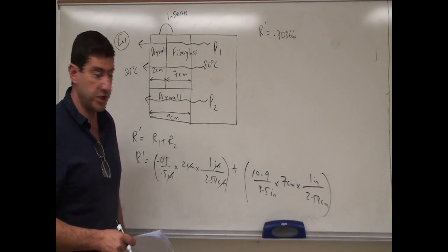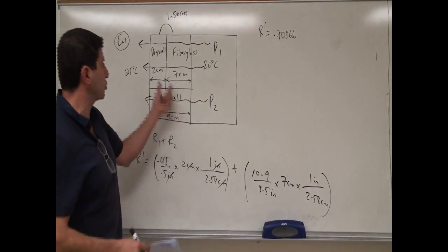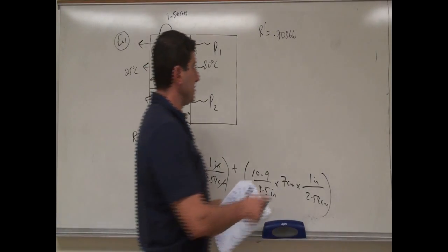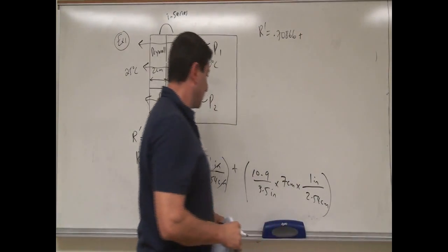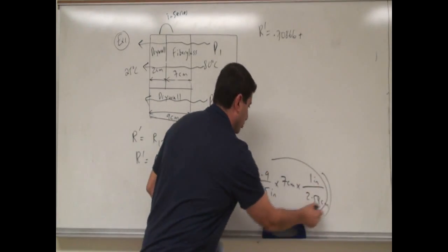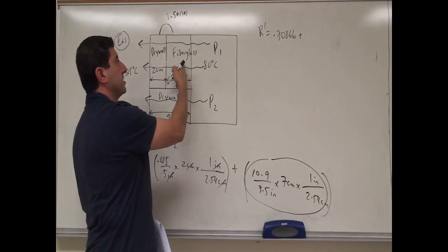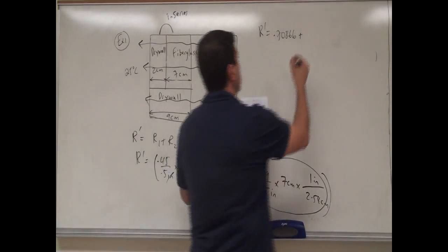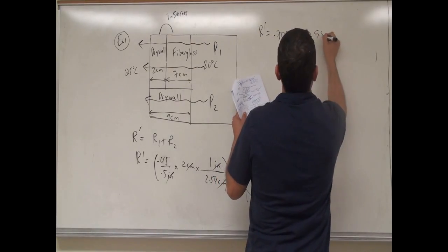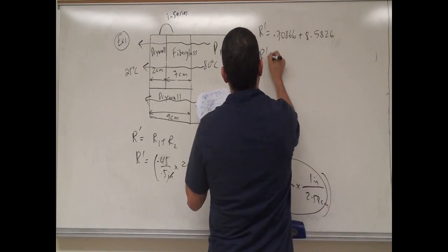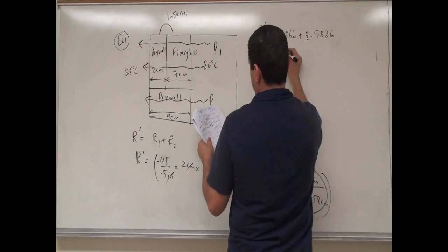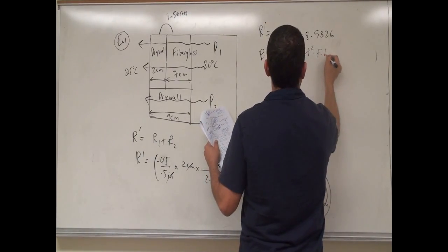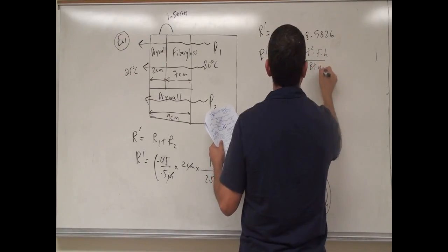That is still in the British unit system because we haven't changed the units of foot squared, hours divided by BTUs, right? The only thing we've done is to correct for the actual thickness of the material. So then you add to that this number, R2, the insulation factor of the fiberglass, and that one comes out to be 8.5826. Then when you do that, you get 9.291. Then it's foot squared Fahrenheit times hours over BTU.